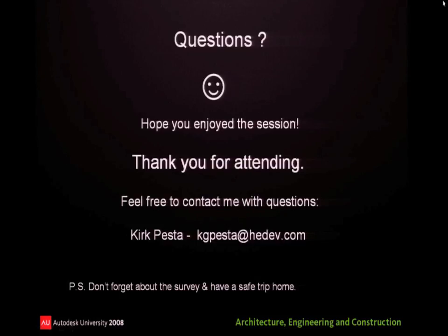And then once you get more into the DD level, you have to come back and check it. You go back to that view and you check it. And then at, say, 3 weeks out, you might run an interference check, but you run it out of the mechanical model because everything interferes with mechanical, right? And our belief is you don't go to Navisworks unless you absolutely have to.